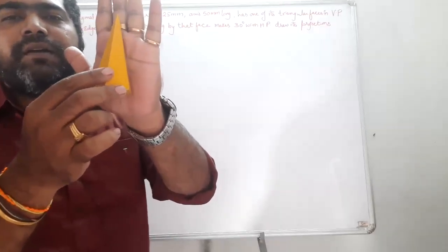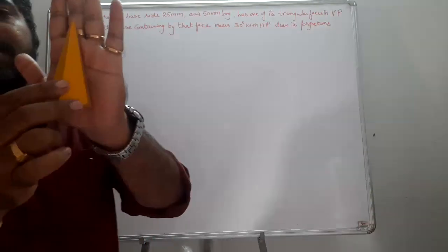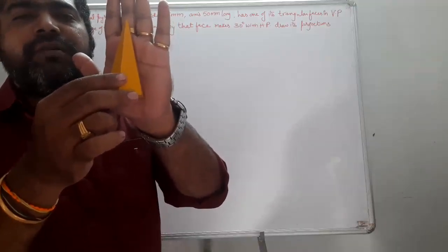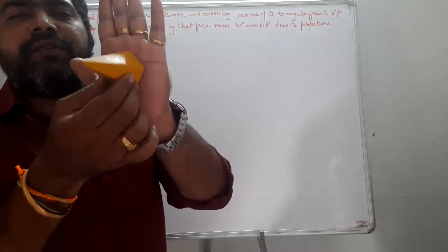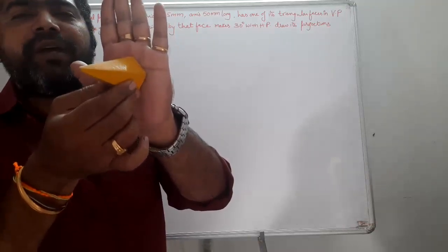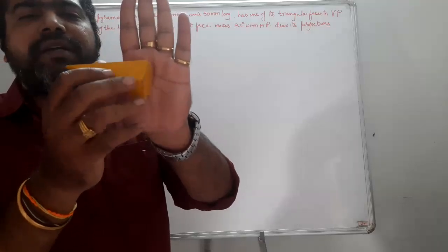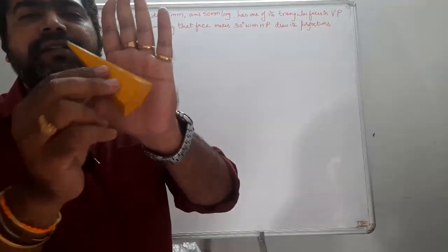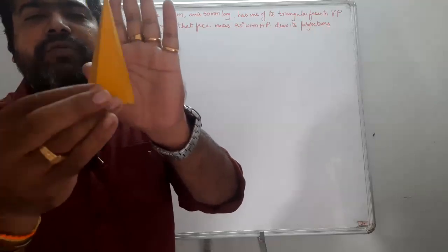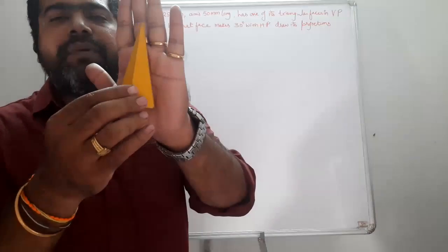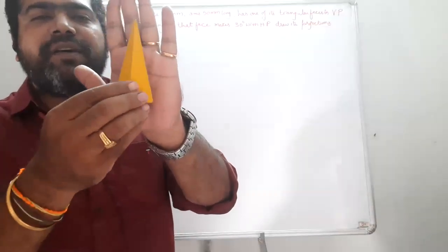So how can you put your simple position? If your axis is perpendicular to VP, then you can make your axis inclined in this manner and put your solid like this. If you are not able to put your solid touching the triangular face like this, why? Because directly we can't place it somewhere here.